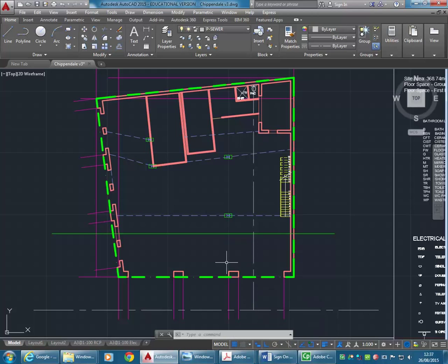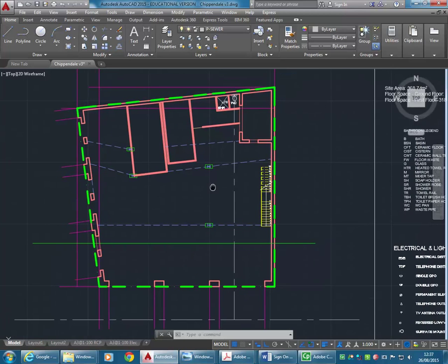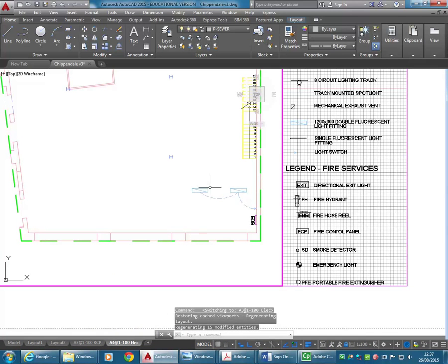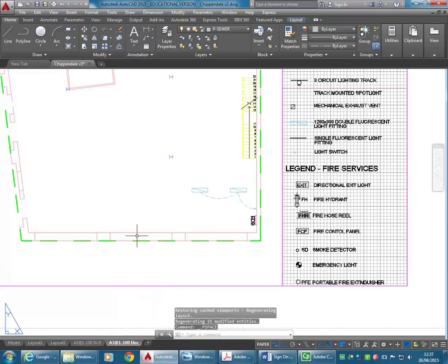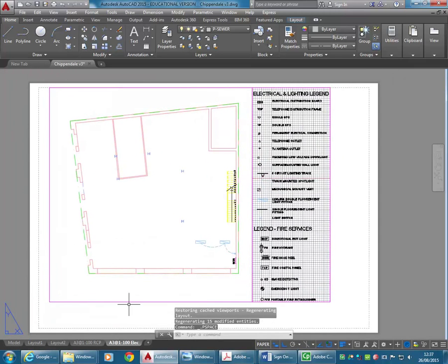And so I think for this, we don't even need to indicate pits or anything like that. I think as long as you've got a line indicating the drainage, then we'll have a plumbing services drawing or drainage diagram, which will be a fairly simple drawing. It doesn't even need to be A3, or it doesn't need to be at scale.